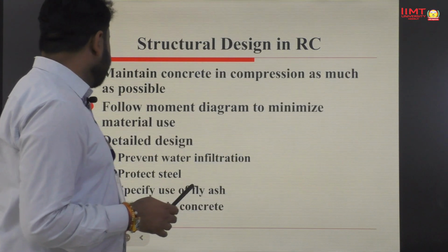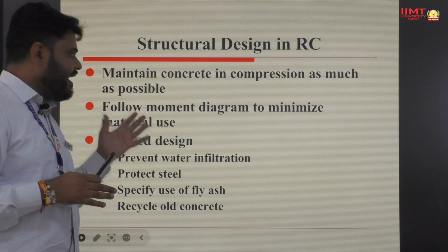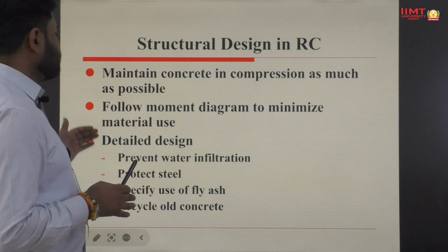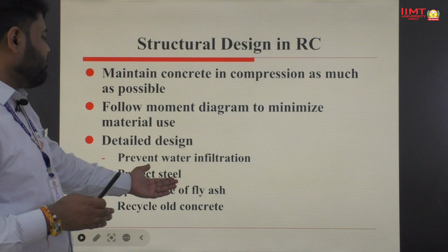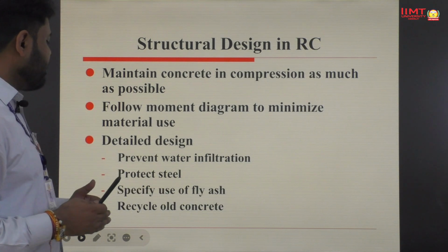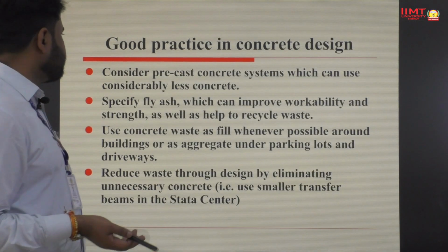Come to the next slide. Maintain the concrete in compression as much as possible. Follow the moment diagram to minimize the material use. We have to detail design, prevent the water infiltration, protect the steel, specify the use of fly ash, and recycle all kinds of concrete structure.